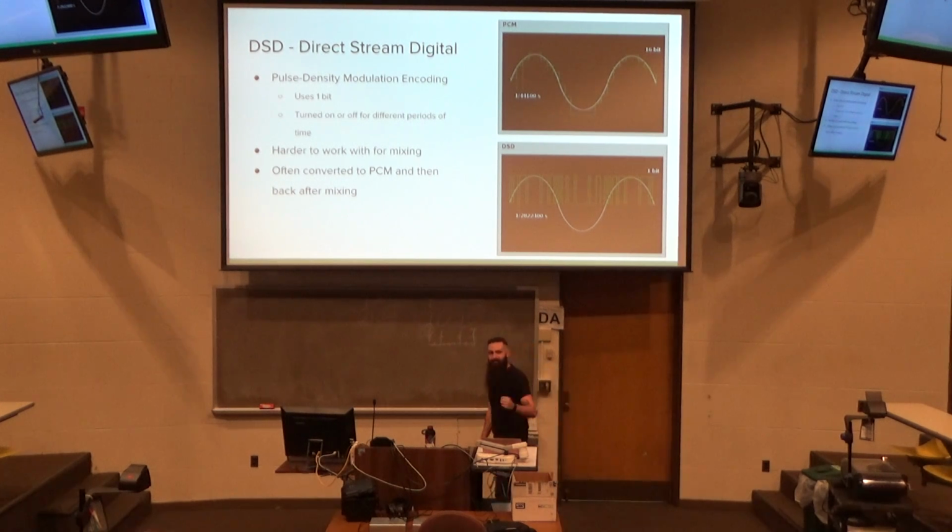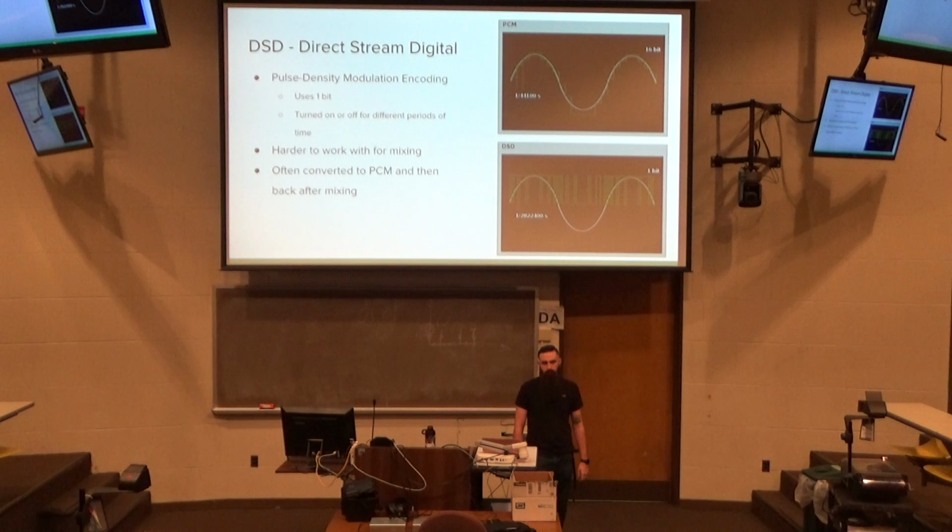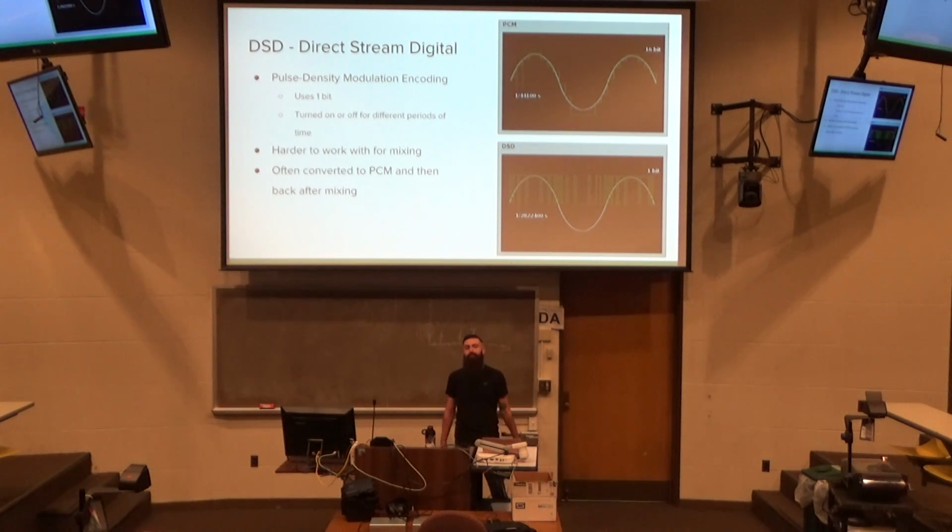Well, say that waveform is 5 volts, and each of your signals coming in are 5 volts, but in order to convert that to a range from 0 to 5, not binary but analog, you split the LSB 4 times, say in this example, and the second to last 2 times, and the most significant 1 time.